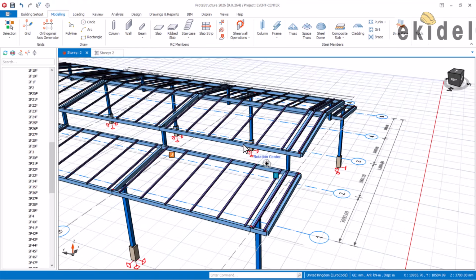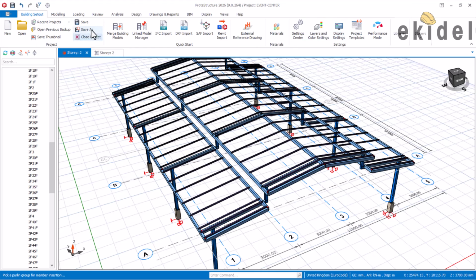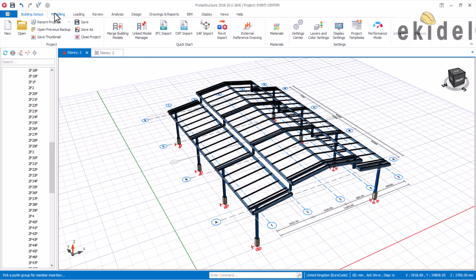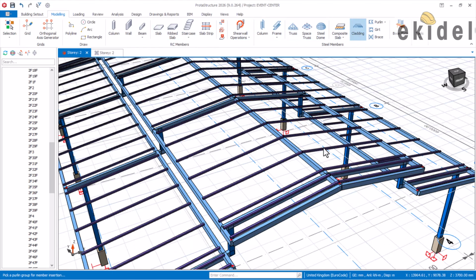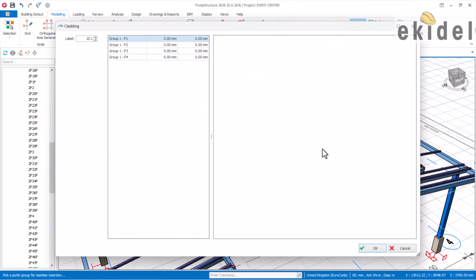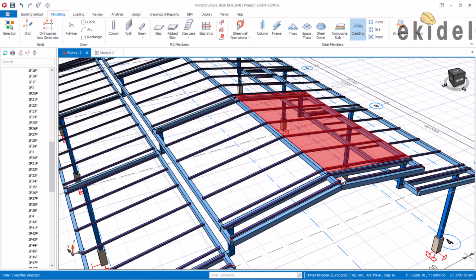To put our cladding now, I'll come here, click on this place here. Now I won't be teaching you guys loading. This is just for modeling. In my next video, we'll do the loading of this steel. We have to apply wind load and also everything. So come now and make sure it's my cladding, then click on this particular place here. Note that we are meant to load our cladding, but that will be in our next video. So I'll click on this now, accept this here, and do the same thing for every other polyline.